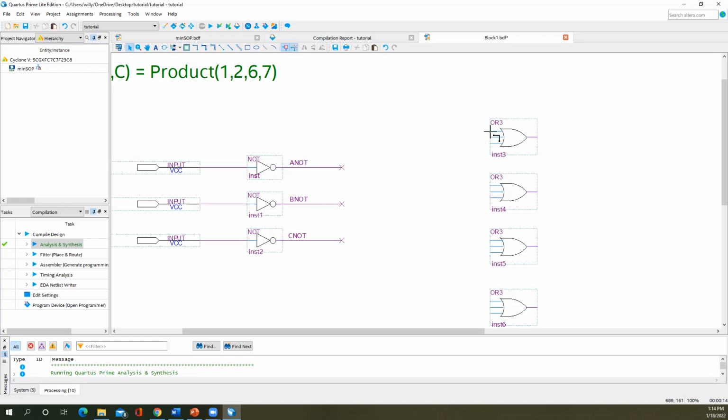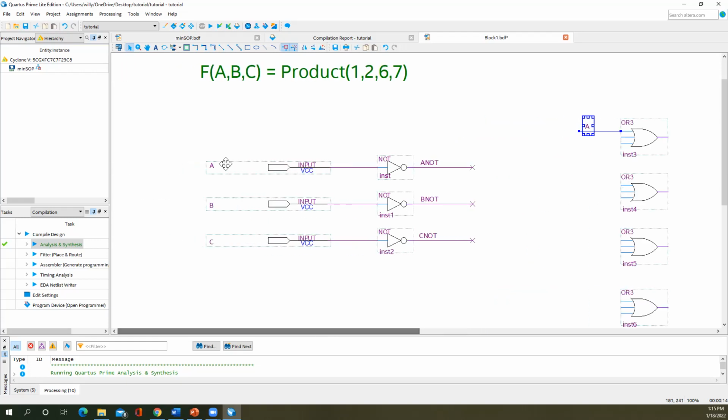What I'm going to do here is move the cursor here. I get the crosshair. I'm going to left click with my mouse, pull this out, and draw a wire. While this is highlighted, I'm just going to type A, capital letter A. If I use the same name as what I've used for this pin here, that is equivalent to if I had drawn a wire from here to here. I'm going to say Control Z to undo. And I'm naming the wires.